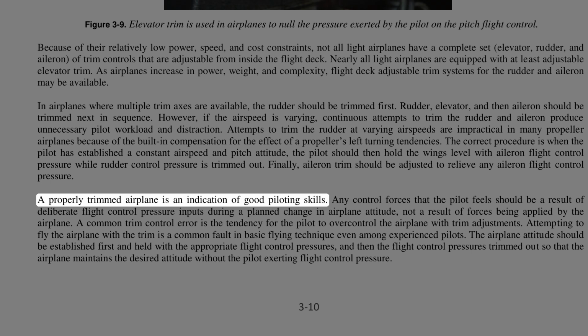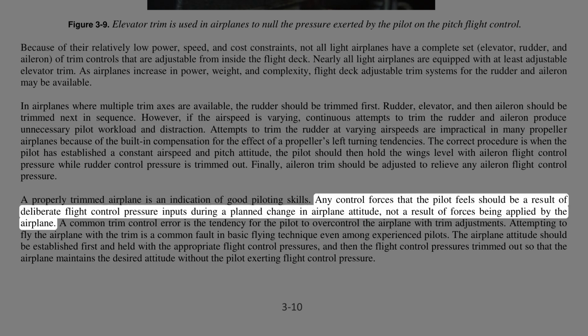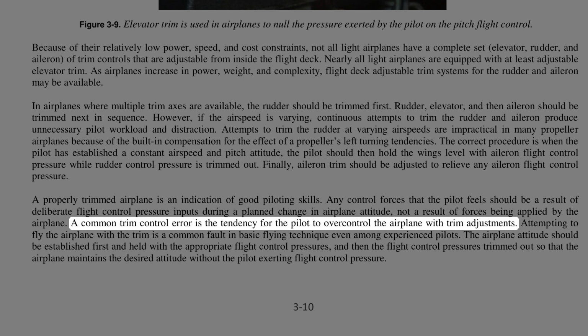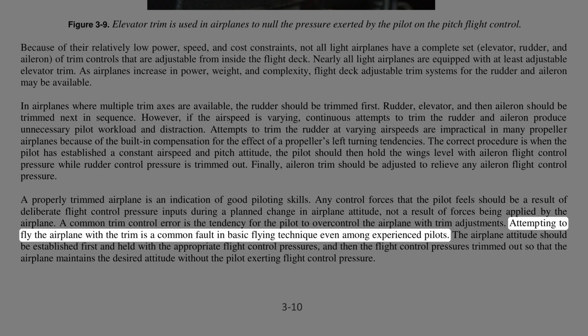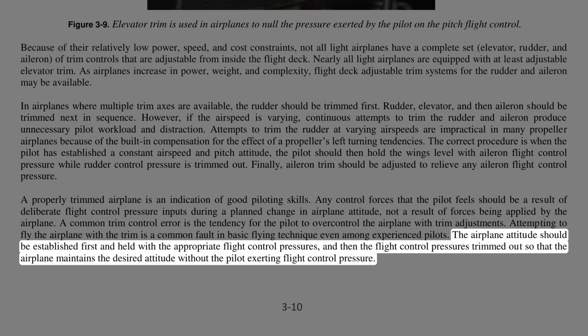A properly trimmed airplane is an indication of good piloting skills. Any control forces that the pilot feels should be a result of deliberate flight control pressure inputs during a planned change in airplane attitude, not a result of forces being applied by the airplane. A common trim control error is the tendency for the pilot to over-control the airplane with trim adjustments. Attempting to fly the airplane with the trim is a common fault in basic flying technique even among experienced pilots. The airplane attitude should be established first and held with the appropriate flight control pressures, and then the flight control pressures trimmed out so that the airplane maintains the desired attitude without the pilot exerting flight control pressure.